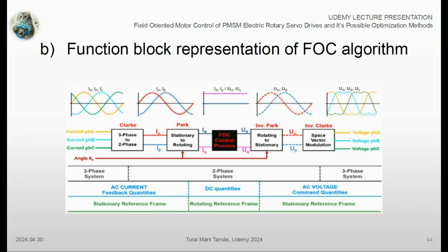You may remember that we shall filter these measured phase currents in order to utilize the base harmonics of them, and afterwards the so-called Clarke transformation can be applied to them. The latter mathematical operation transfers the measured three-phase current system to a two-phase coordinate system.